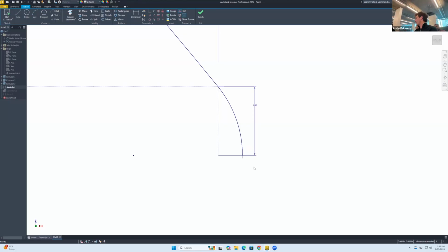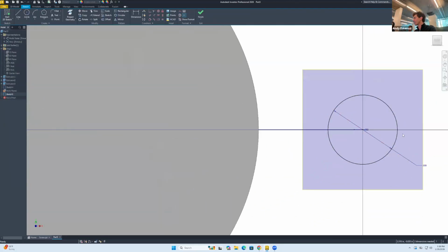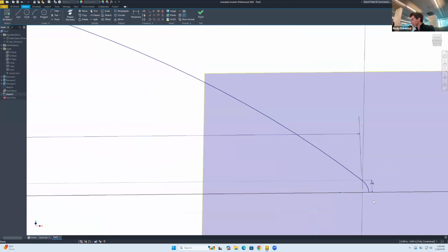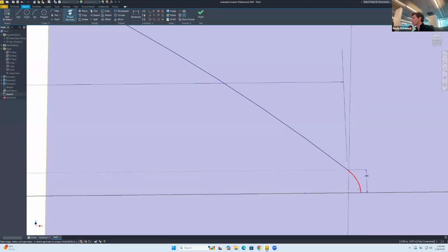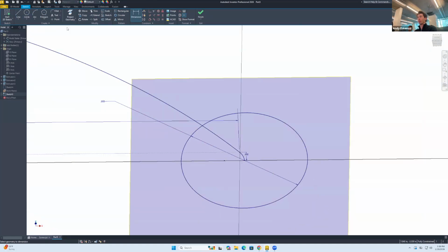Yes, it appeared out of nowhere. However, believe me, I know this is dark magic in here. When we go back to edit the sketch, I'm gonna get rid of that circle. What we can do is go here to project geometry. That point, there we go. Now I'm gonna do circle from here. And we're gonna make this 0.5. Okay, moment of truth. 3D model, sweep.